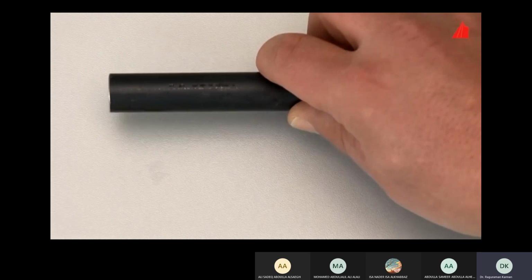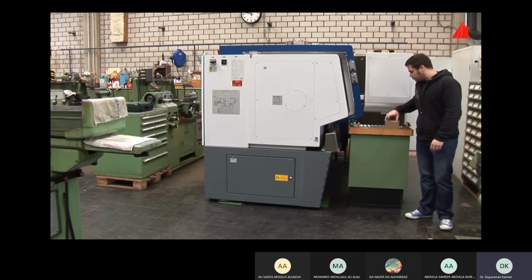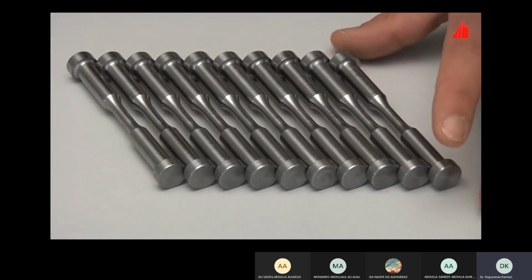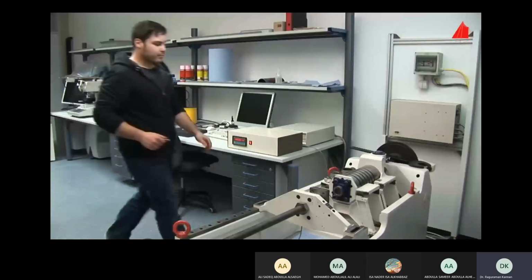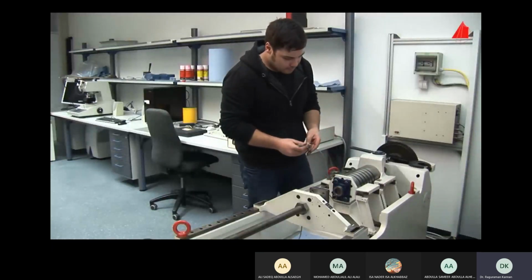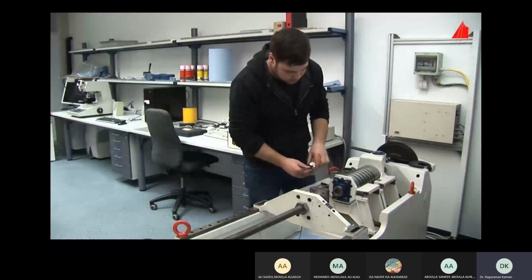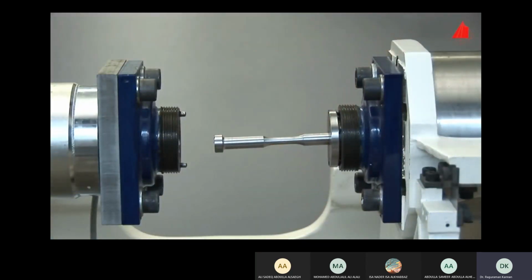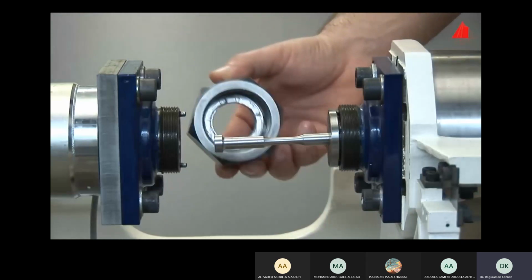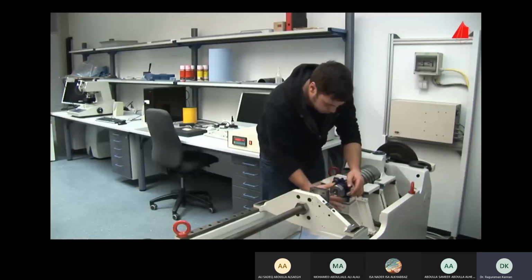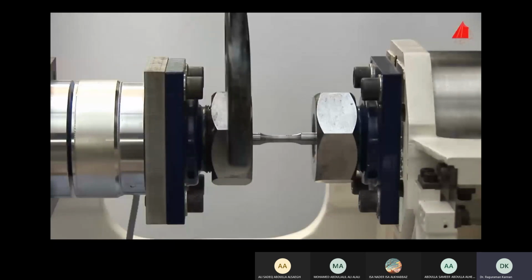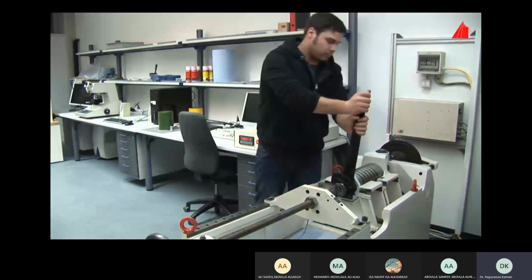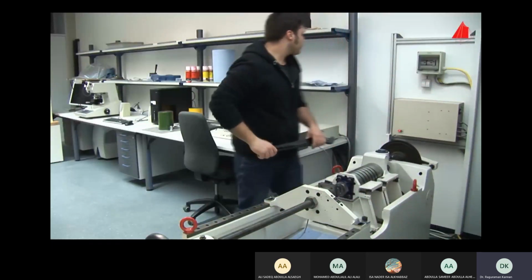The material tester goes to the workshop to get 10 specimens manufactured from the rods, not just one. All of the specimens are as identical as possible. Back in the lab, he has all specimens ready for use and picks out the first one. He mounts the specimen carefully and securely into the fatigue testing machine. Together with 2 half shells, he inserts one end of the specimen into the right specimen grip. With a union nut, he locks the right end of the specimen. Likewise, he mounts the left end of the specimen into the left specimen grip and tightens the nuts. The preparation is now complete.